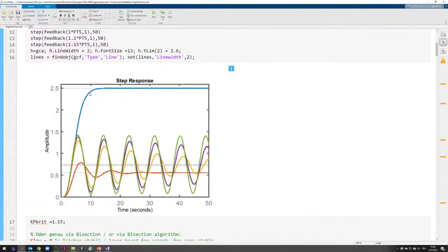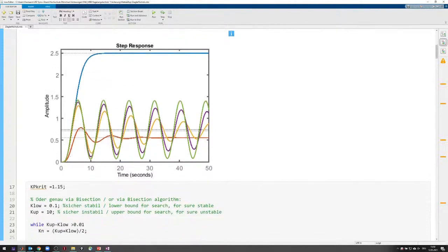Around that system, I'm doing a proportional controller. So I'm closing the loop with a proportional controller, and the first shot is this orange one. So clearly this orange one is far away from getting unstable. Well, not so far away, the damping is already low. And then I started to increase the gain, and you see this yellow one is also not unstable because the oscillation decays.